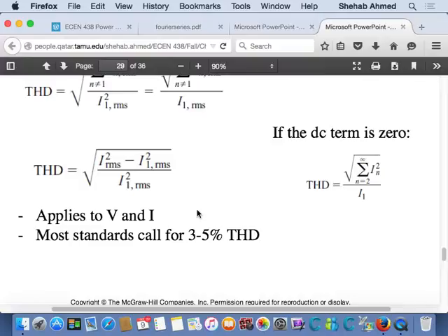So if you have capacitors in your system, you're actually switching. If you have motors that you're turning on and off without a drive, you're actually turning them on or off with a switch. So this switching will cause abrupt changes. Anytime you have these abrupt changes, you will cause harmonic content, right? If these abrupt changes are persistent, like you have a power electronic device that's always there, like a UPS or a motor drive, these things are always there.